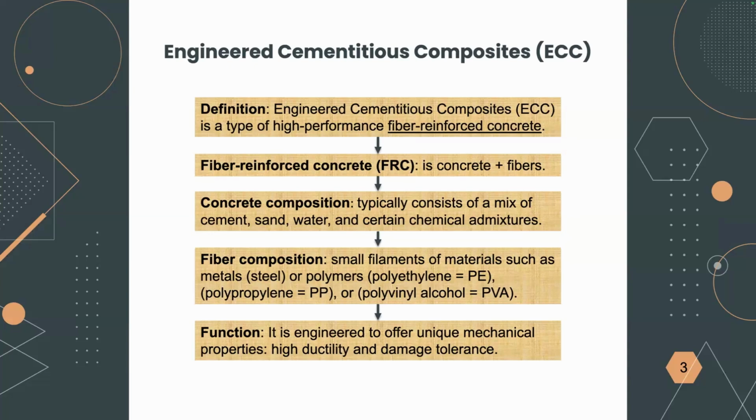And we have another advantage, which is damage tolerance. So what do we mean by damage tolerance? Simply, concrete has some temperature or shrinkage effects, which create some cracks on the surface of concrete. These cracks open the way for water to go inside and attack steel rebars or steel reinforcement. And this would deteriorate the structures, making the steel rebars have section losses, and it will reduce the structural integrity of our members.